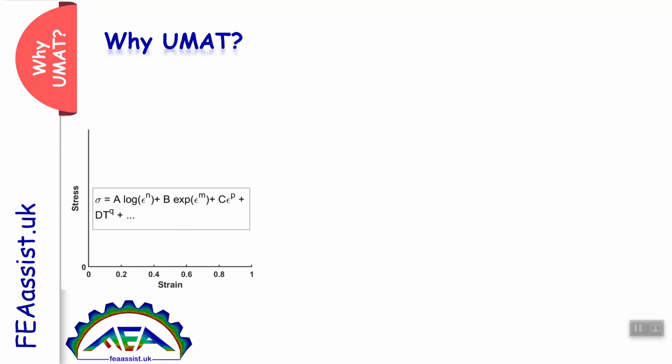So what can you do? Then you need a place to write this equation or your equations and tell Abaqus to obey this behavior to solve the problem. This is the reason we need VUMAT, because our equation is new.